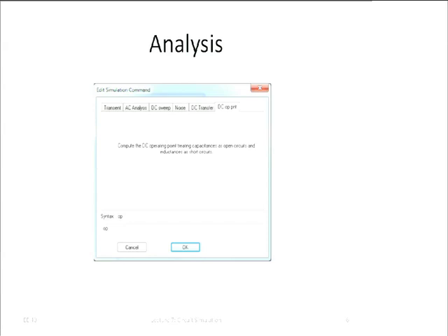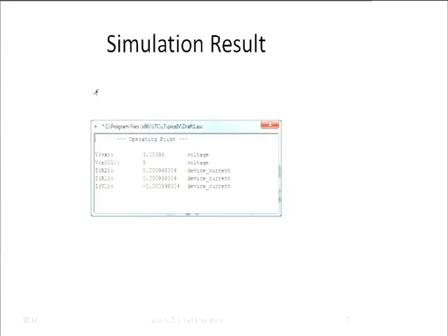That's still there, right? And you click OK, you run it, and then that's what you get. It tells you for every node, there is a node Vx, there is a node. So let me get to the schematic to what this really means. So there is a node, a common node. Well, that is 0, and SPICE doesn't bother telling you that the voltage here is 0.